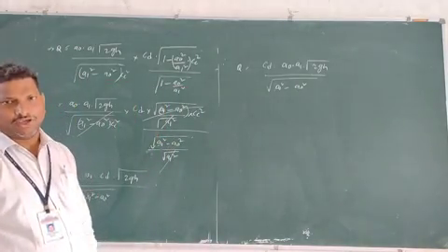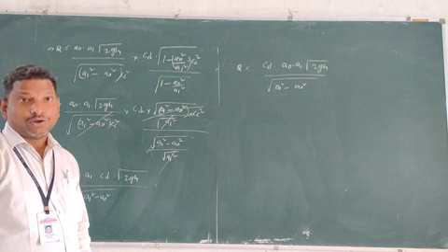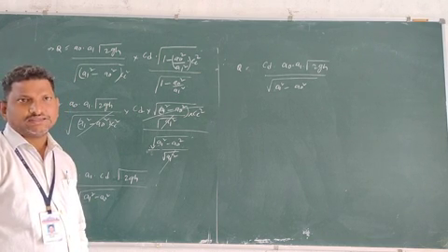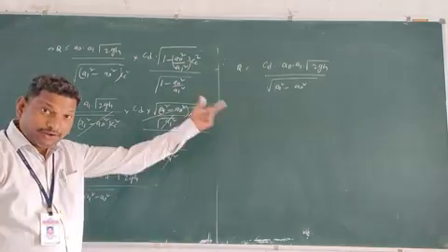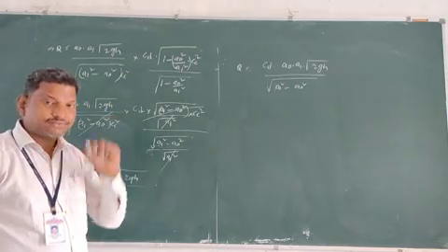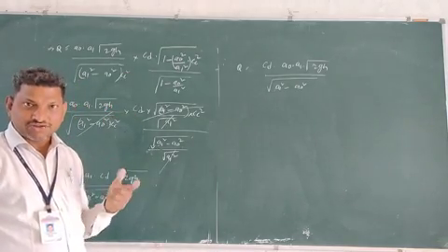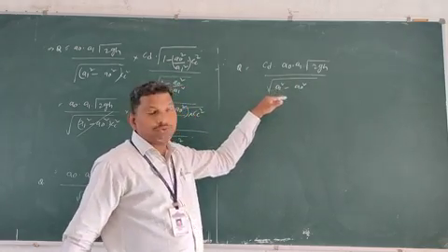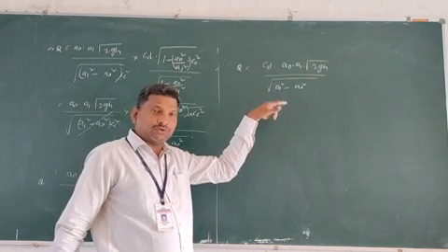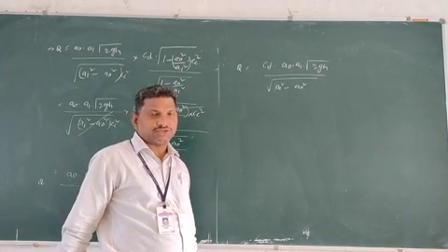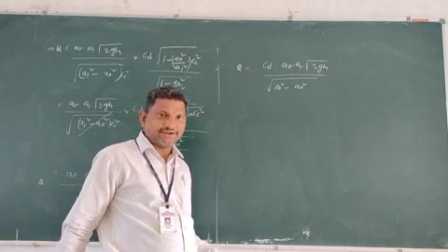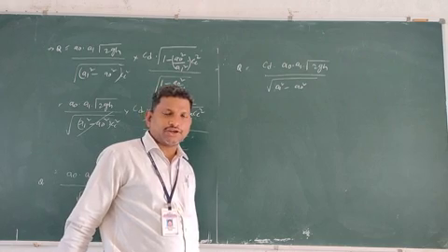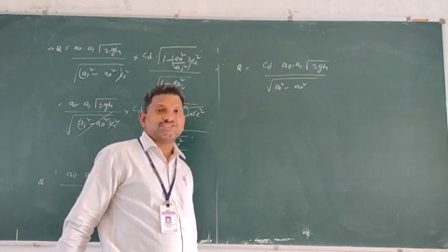If you observe the discharge equation, the previous equation, in terms of coefficient of contraction, the expression is different: A0 into A1 into square root of 2gH into Cc divided by 1 minus A1 square minus A0 square into Cc square.